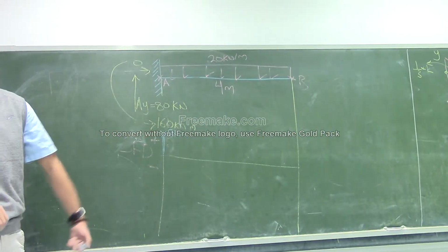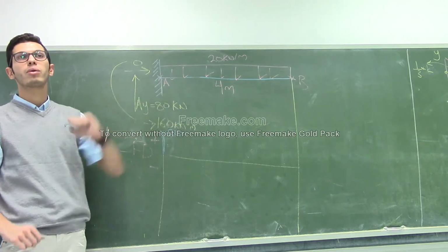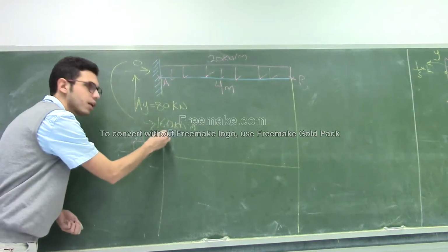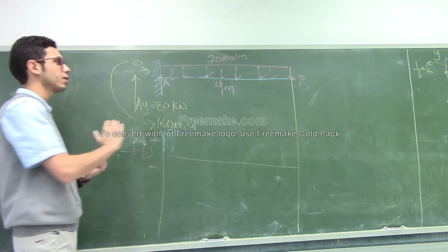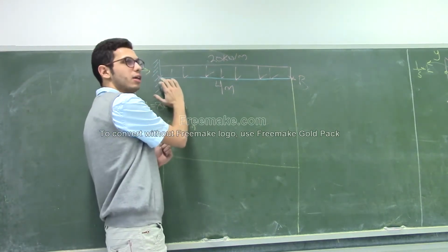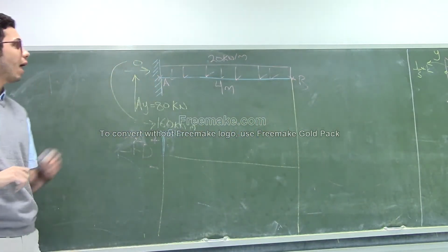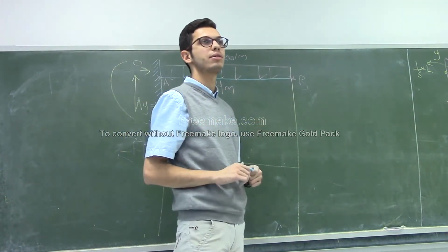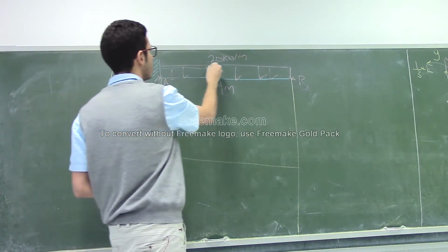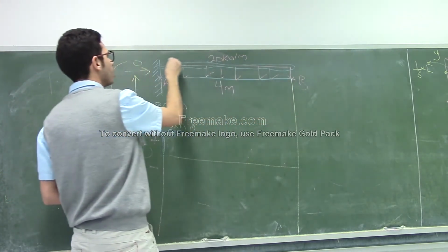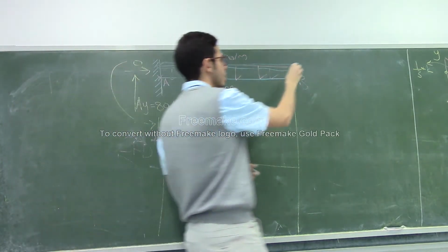So again, at the point A, the reaction was 80 upward, so I should go up here 8 steps. Is that clear for all of you? Yes. Okay. After that, when I move from point A to point B, there is a distributed load acting on the beam, and this distributed load is a rectangular one. The line of the rectangular one is a constant.